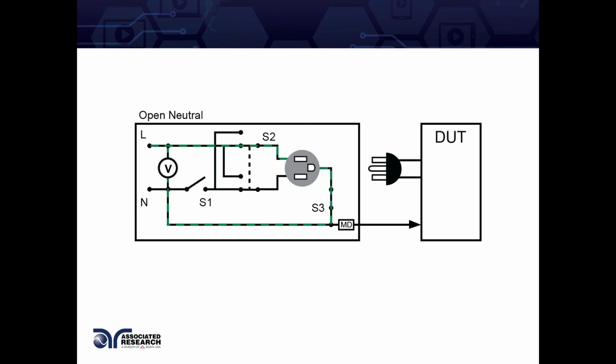The way I like to explain leakage current tests to anyone is that it's all about putting the measuring device circuit in the correct position, the right spot. That's achieved by those different probe conditions that we talked about, and we'll look at those in a circuit diagram shortly. With the open neutral condition, obviously the device will power down because you've broken the neutral connection, but there still could be some leakage flowing because the neutral is sometimes grounded and the line is still active.